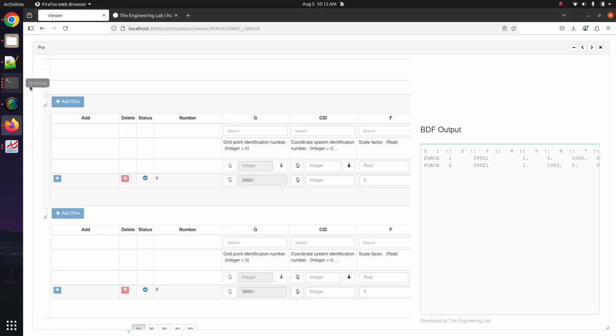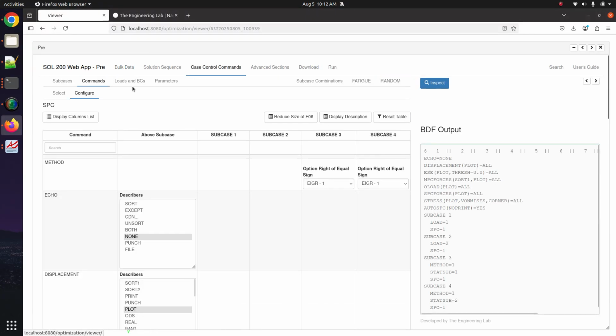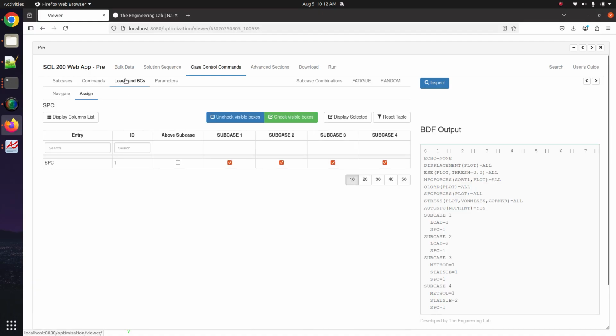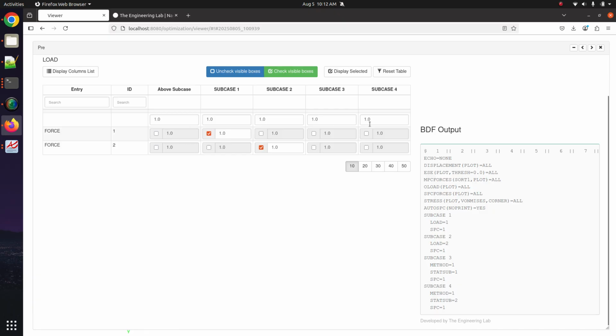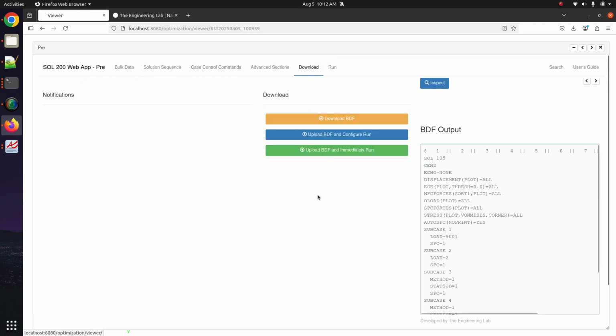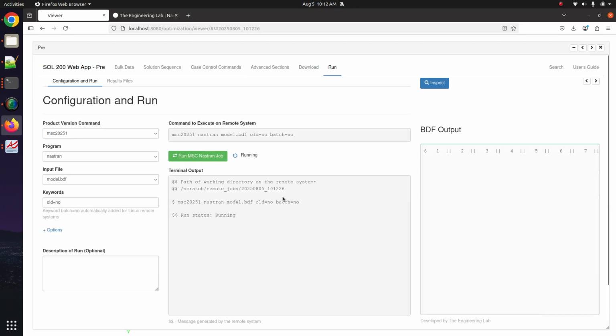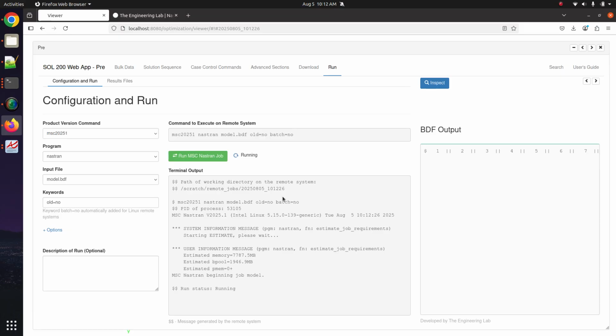You could scale up the scale number for the load case. So if you go to loads and BCs, go to navigate, go to the load section, and here you could take the loads. Here, I believe we're doing this for subcase 1 and subcase 3. So here you could say, you know what? Multiply all the loads by 242. And let's go ahead and rerun the analysis. So I believe we should get 1.0 there. And then maybe we'll try that for -1 also. We'll try when the buckling load factor is -1.